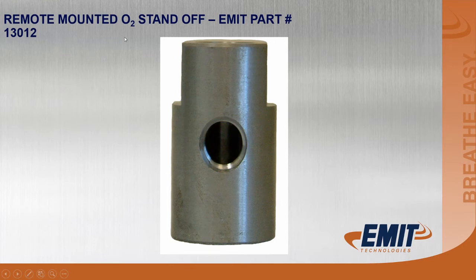This is a remote mounted O2 sensor standoff. We would use this like we showed earlier with the Waukesha 7044s. They work great in the wide pipe, but if you don't have that option, you can use a remote mounted O2 sensor. I strongly recommend doing whatever you can to locate them in the wide pipe, whether it be drilling or otherwise, and tapping in the Y pipe between the turbos versus using a standoff. The standoff is always the last resort.